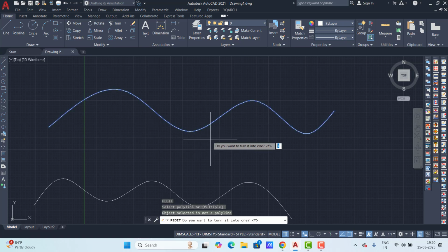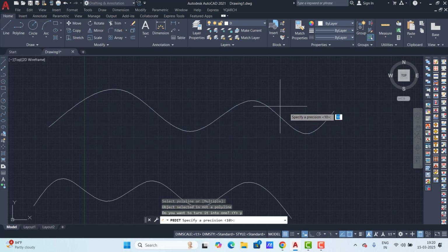Now do it. Suppose this length goes, and here I want to make an arc. So just press A enter, and the same, give some space. Here only this type is possible. If you make ortho, ortho means this type of elbow can be made. Now to go straight, again press L, and ortho is activated this way.